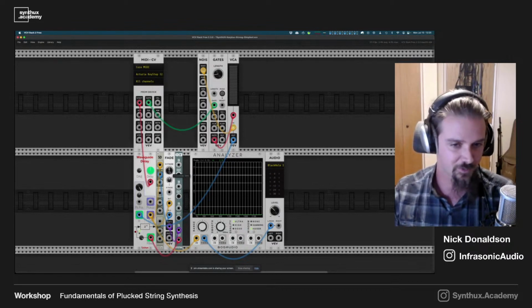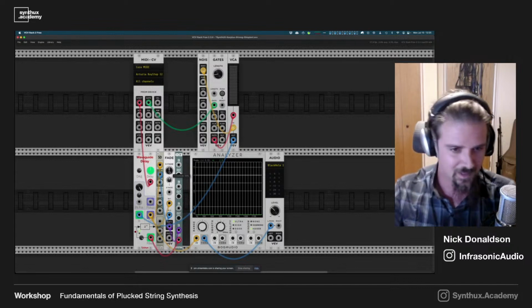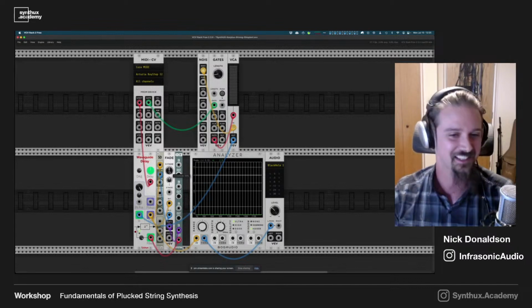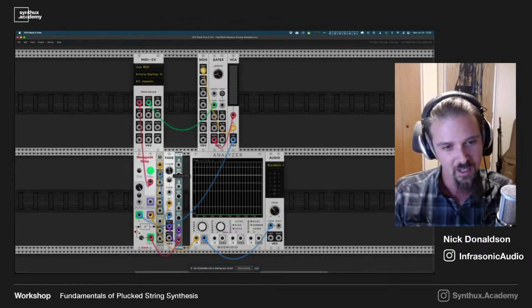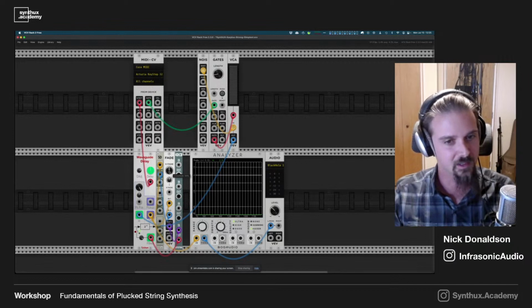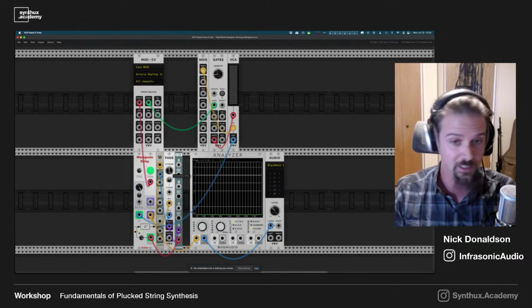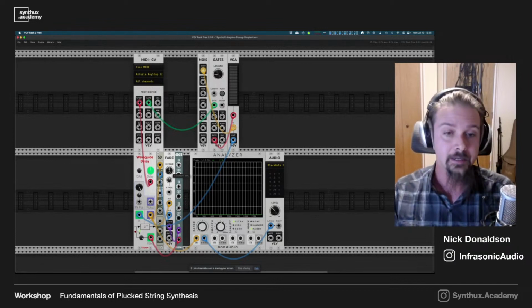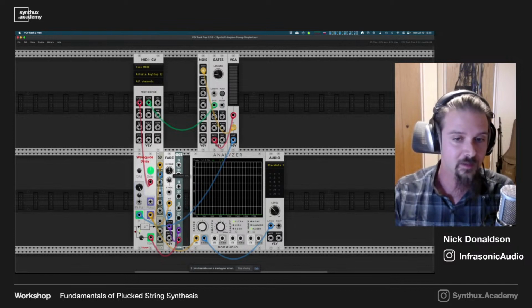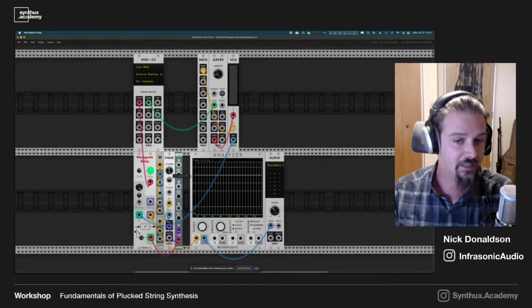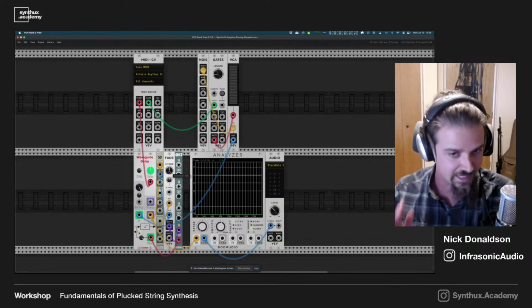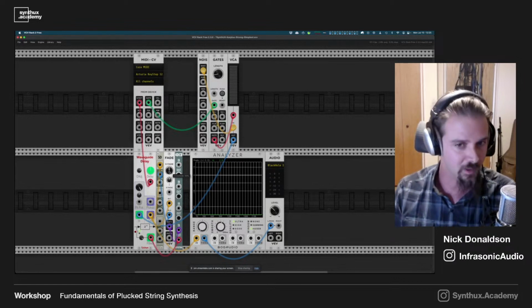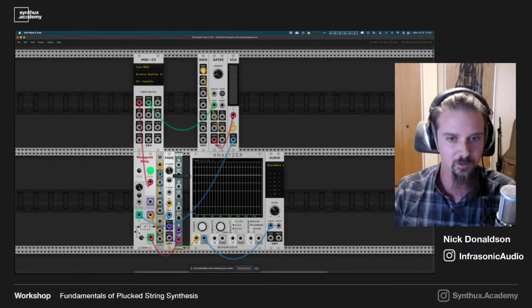Essentially, this filter is really simple. It's just an average of 2 samples, and like you mentioned, you can do these things in VCV Rack. You have to think a little bit differently about it than if you were doing this in, say, a computer music environment like Pure Data, Max/MSP, or SuperCollider. Then you generally have access to those lower level surgical tool abstractions. We have an exact perfect delay line. We can do a 1 sample delay. We can do an arbitrary multiplication.